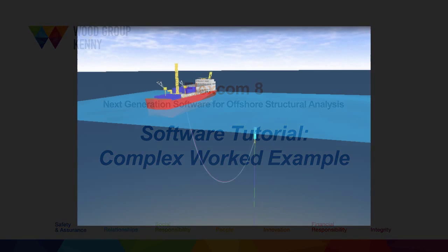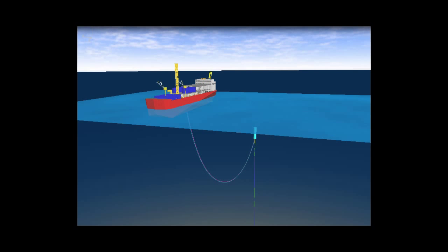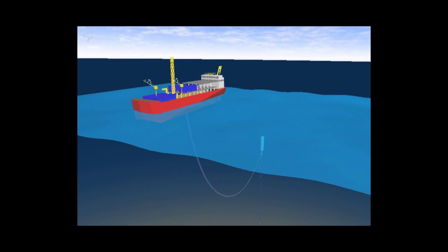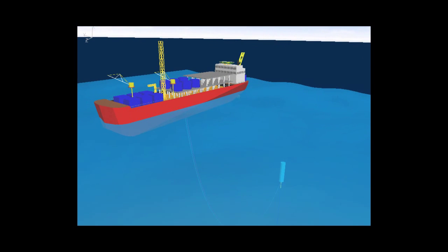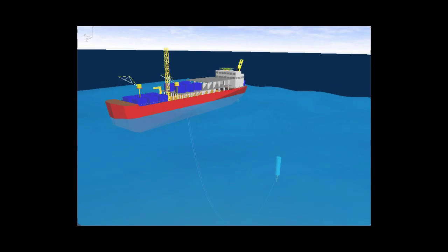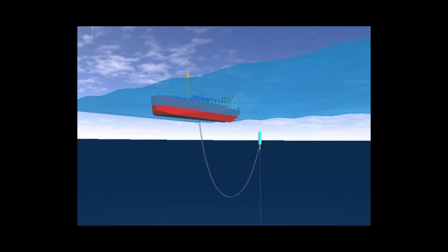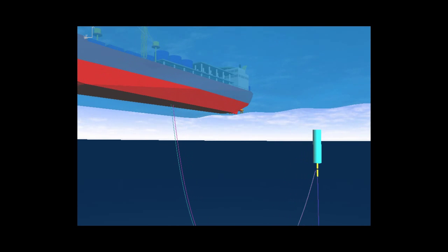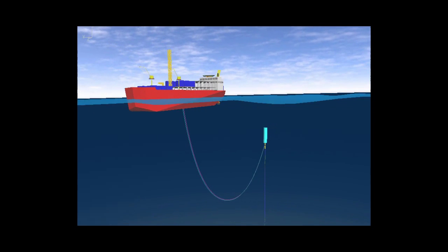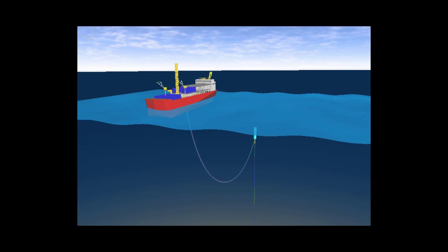This worked example considers a freestanding hybrid riser arrangement. This is a complex model which includes a dual-bore vertical rigid steel riser tensioned via a buoyancy tank, with a connection to an FPSO through two flexible jumpers. Once the structural configuration has been obtained statically, a load case matrix of various vessel offsets and wave periods are considered.